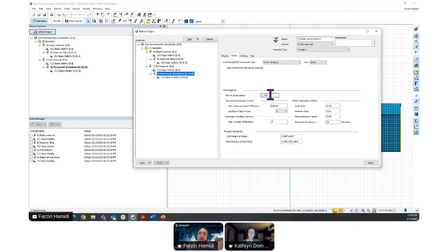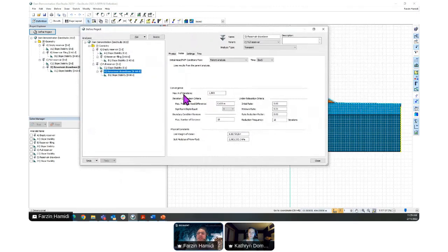The thing that we typically suggest to the user is to either play with the iteration, because maybe we need much more time for the problem to run. At this stage, as you can see here, the maximum iteration is 1,500. So you can even increase this iteration, or you can play with these two other convergence parameters.